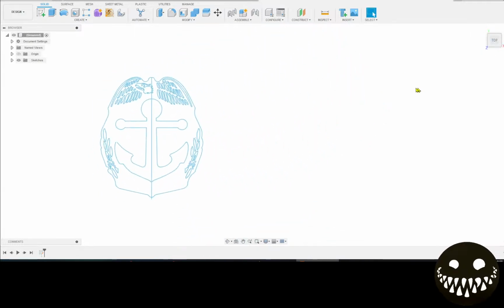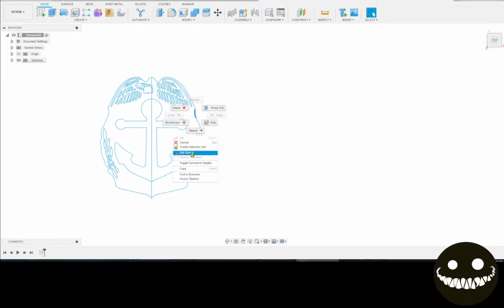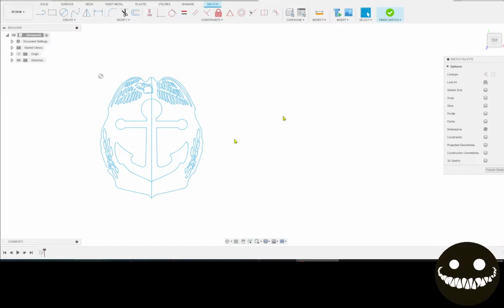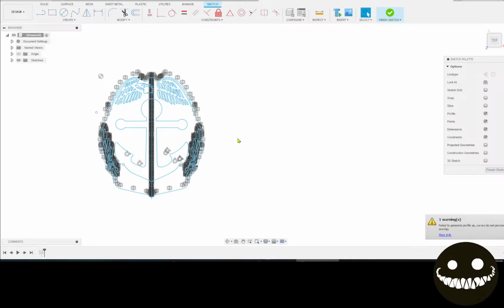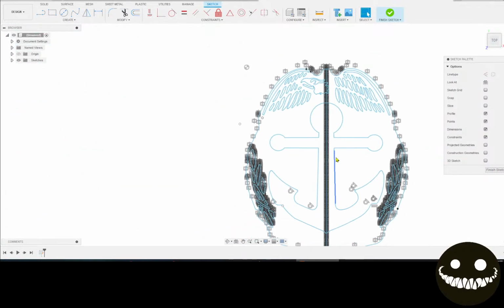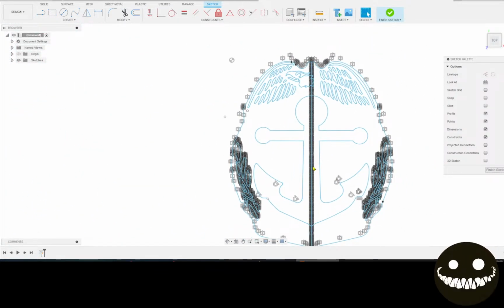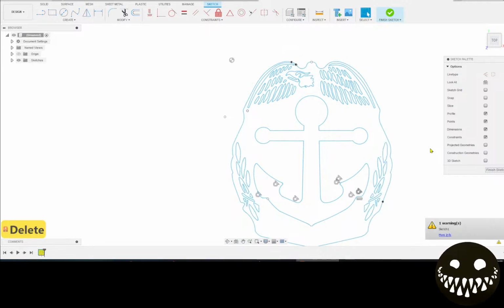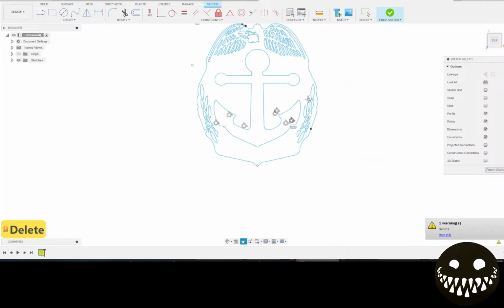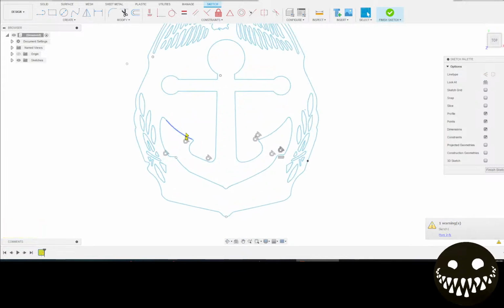So we'll go back to profiles here, or go back to edit this. And I actually crashed when I originally attempted this, not on video. So I'm going to bring up the points in the profile and the constraints so I can see all the action that's happening. And I'm going to delete this parting line in the middle, which is the mirror line for all these constraints. And it's just going to make this drawing way less heavy. We don't really require that right now.